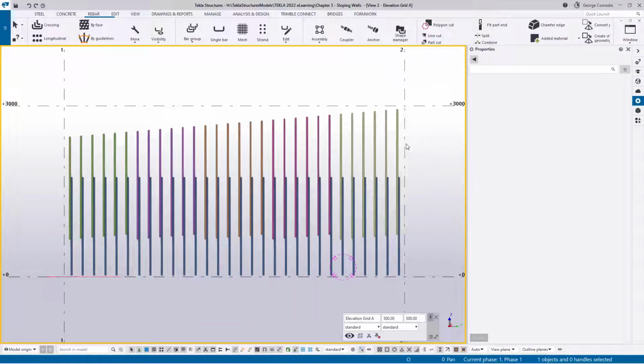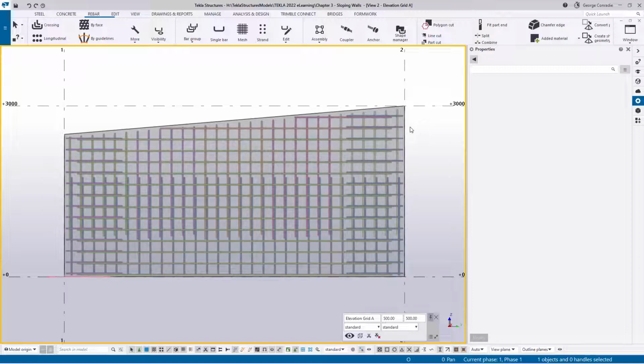If we start on this side, you can see the colors, there's 6 in that, and I'll put off my highlighter. There's 6 there, there's 6 there, 6 there, 6 there, and that's 6 as well, but it could be whatever the remainder is. But that's the way that you can sort of optimize your reinforcement and get less number of bars.